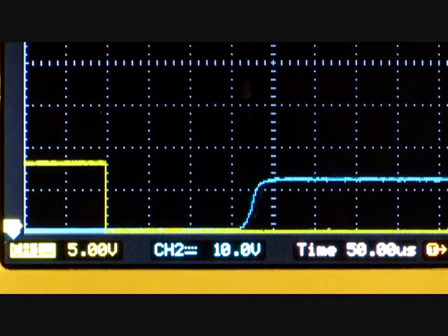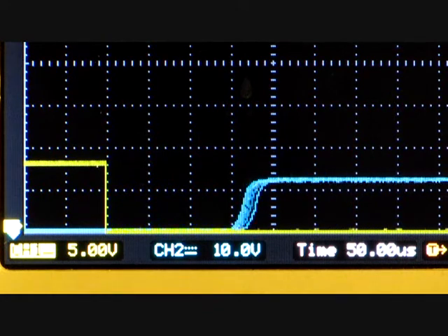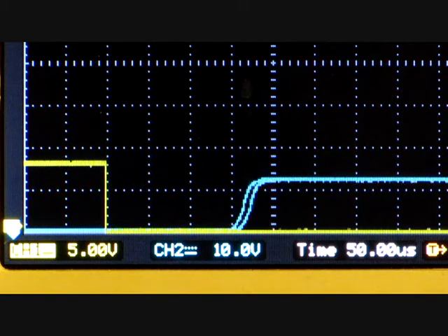Okay, here I have a 812 hertz signal going into the system. It really shouldn't matter what the frequency is going in. The point here is the processing delay. We're set up at 50 microseconds per division here, and there's 3, and well, we'll just call it 150 microsecond processing delay.